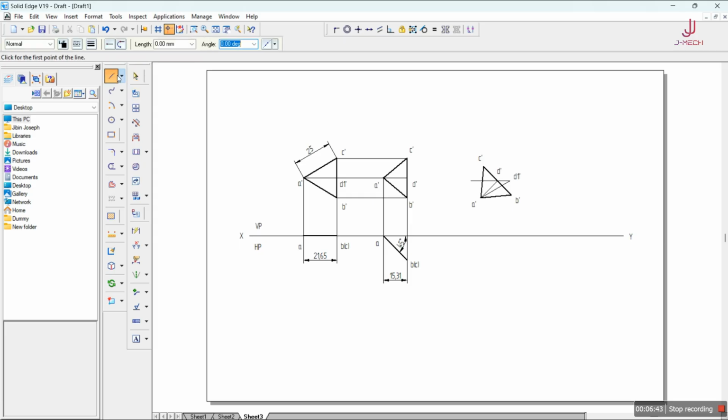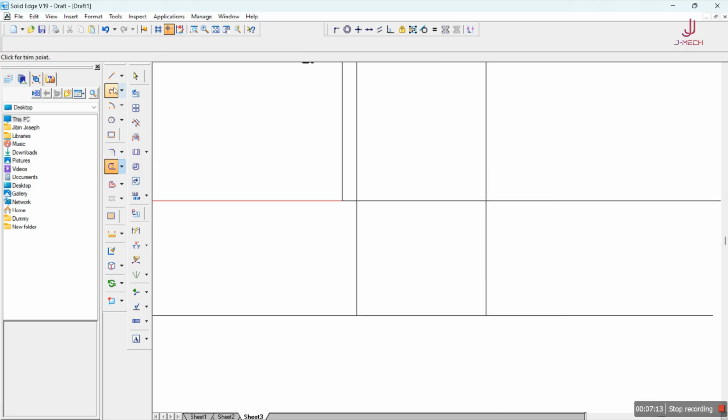Now we'll project the line downwards to the projection of the top view onto this side. From point A to point A, from point B to point B, directed at the bottom, C to C here. It is not making straight, so draw a bigger line and then trim the lines. Now, to draw this, I will zoom this particular area and connect the lines with the visible line.